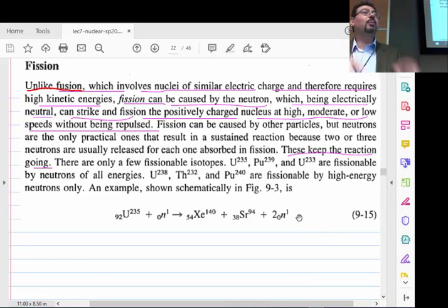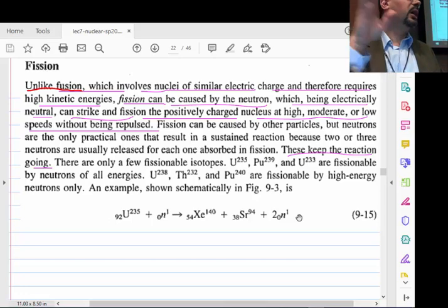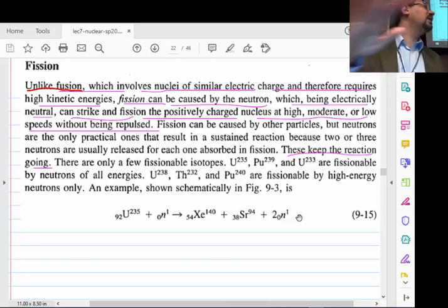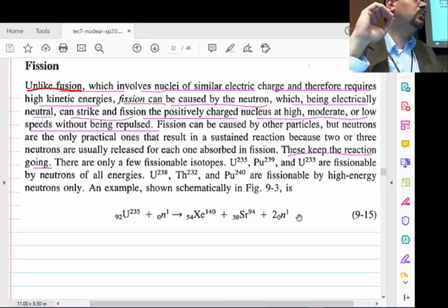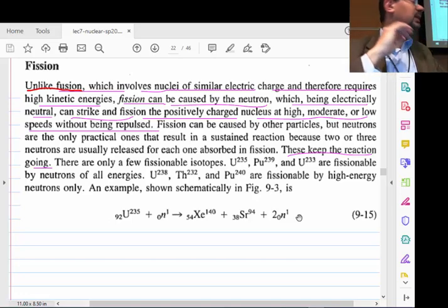If you keep one of them going, so every reaction generates one neutron that hits the next one, this is called a chain reaction. If that chain is maintained at steady state, the reactor will always generate the same heat. Then you can use that heat to boil water, and once the water boils, you get steam into a turbine and generate power, or turn the propeller of a submarine, or whatever mechanical work you would like to do. But the key is that you have a chain reaction. Alright?